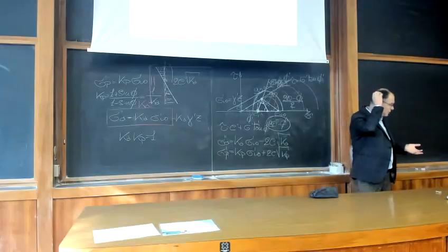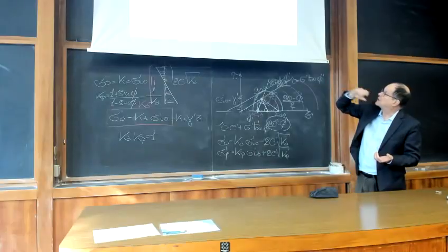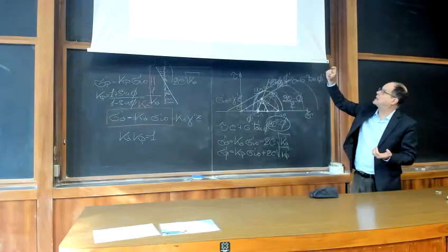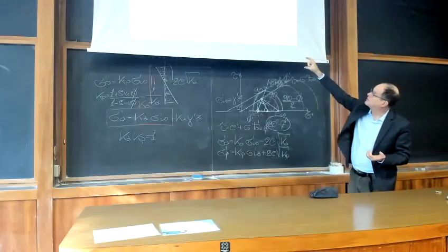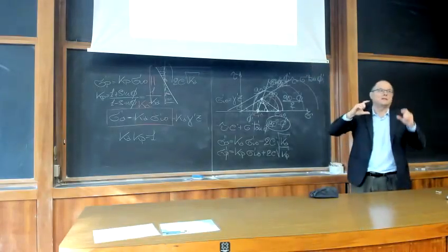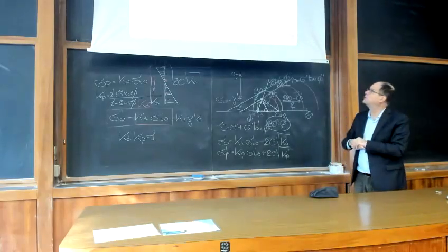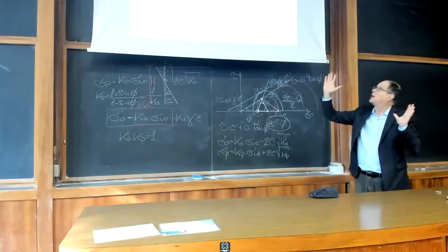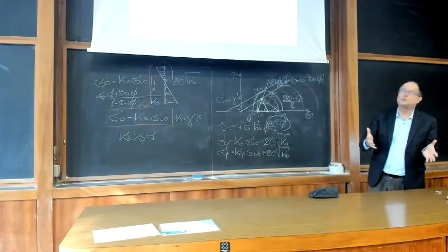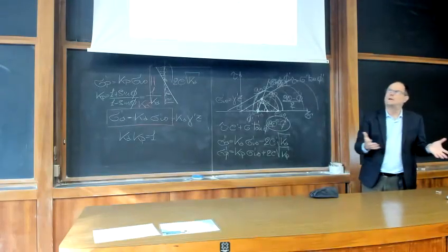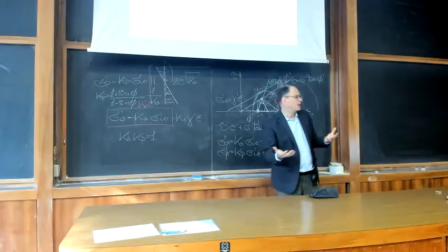What is a shallow foundation? It is what you can see on the left-hand side of this slide. According to Terzaghi, a foundation is shallow as long as the depth of bedding of your foundation, that you can see Df, the depth below the ground surface at which you find your foundation, divided by the characteristic breadth of your footing, B, is less than 2.5. But this is just a geometrical definition.